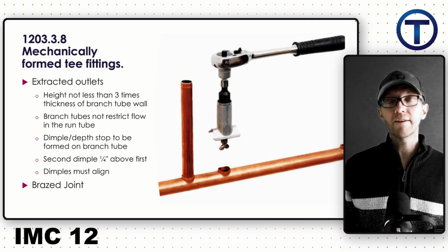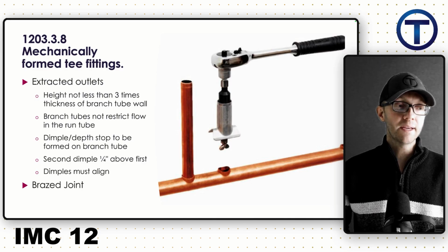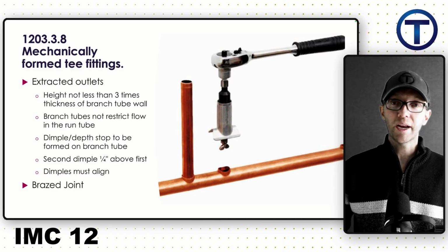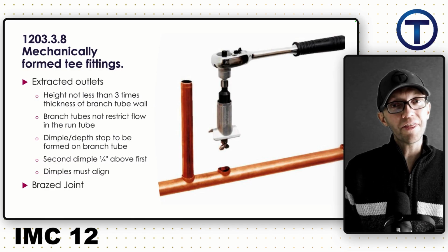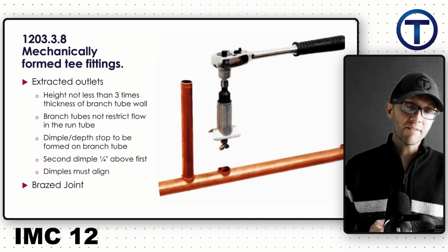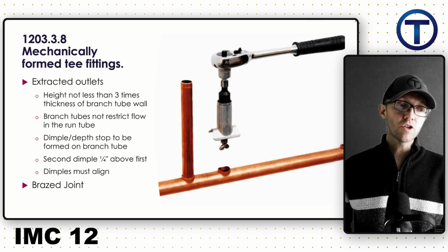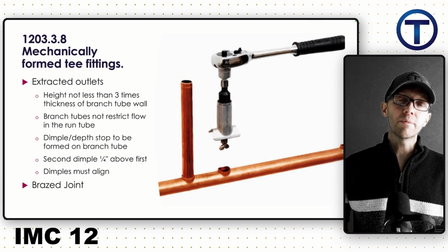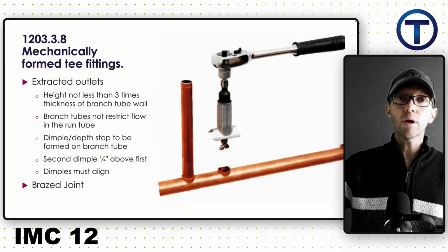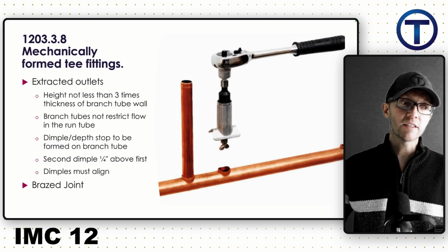But here's what is required if you're going to extract a T and then if you're going to braze that up. It has to have a height of not less than 3 times the thickness of the branch tube wall. These walls are not that thick, but we need to get that T raised up high enough that we have some real connection between the pipes. The branch tubes should not restrict the flow of the run tube. That means if I'm inserting a tube down into that T that's been pulled, I don't want to push that pipe in so far that it starts blocking the flow of the pipe it's connecting to.